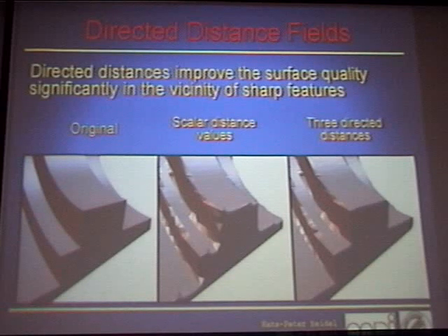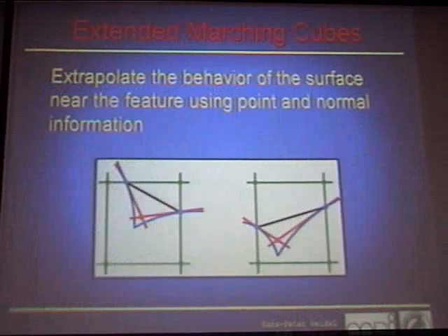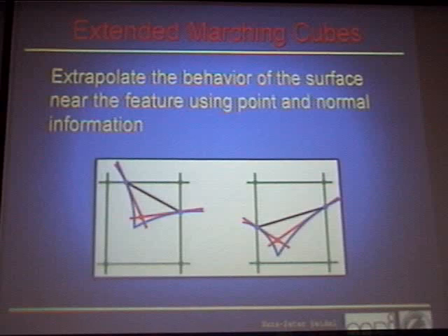In the middle, you would see the result of an isosurface reconstruction using the marching cubes algorithm. On the right, you see a little bit of an improvement, but still it's completely unacceptable in a sense. And this is now where the second ingredient comes in. What the marching cubes algorithm does in these instances, this is a 2D example to just get the idea across: blue is the original surface, black would be the result of the standard marching cubes algorithm.